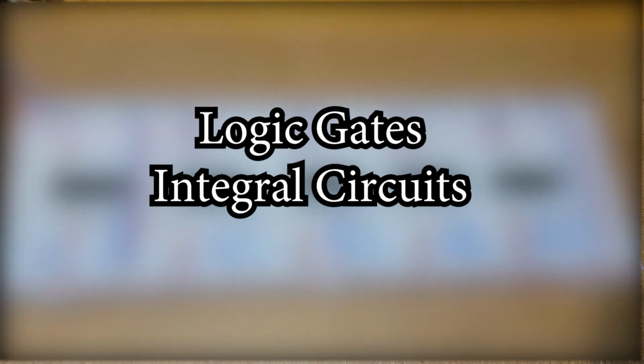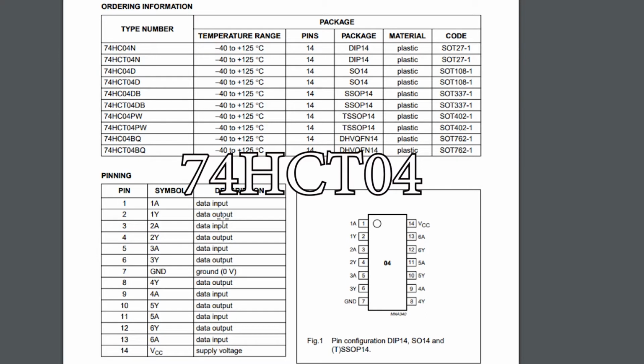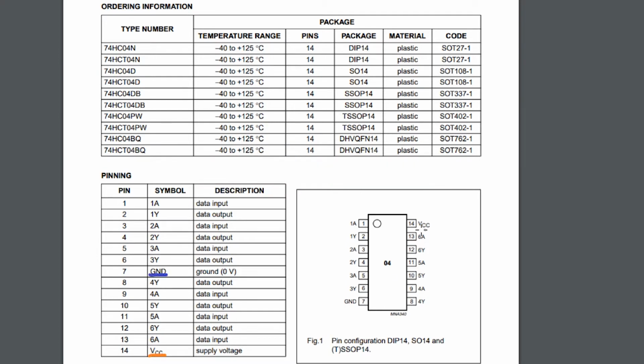This is a look at the electronics behind logic gates. This is a 74HCT04 hex NOT gate integrated circuit. It's powered by 5 volts at pin 14 and grounded at pin 7. It has 6 inputs and 6 outputs. Therefore, it's made out of 6 NOT gates.